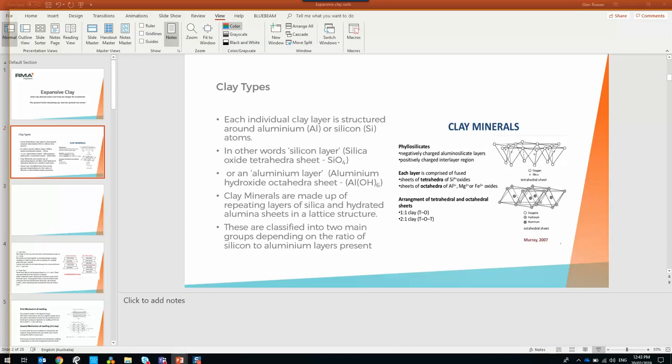Here's again the grading floor. This is fully suspended on Bondeck. That one used timber piles, which I like as well, because they're a small diameter and they're quite smooth and don't give the clay much of a purchase to pull itself out of the ground. If you're not sure what void former is, that's that pile of cardboard over on the side there.